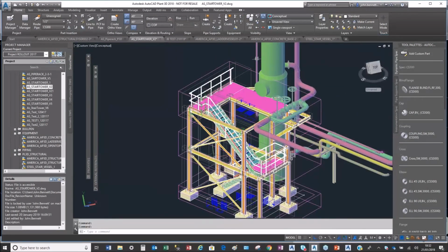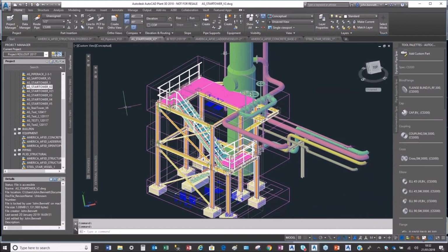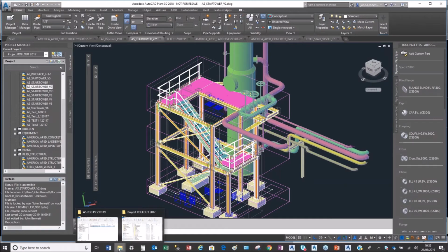Now in that instance, like I said, I just used the file as a reference. So I used this X reference here and the other one to create what I wanted. So I didn't use the SMLX file to export it, but I just worked with it. And the important thing is that I put it inside a Plant project as well. So it was linked to that project. It's actually stored inside that file structure.